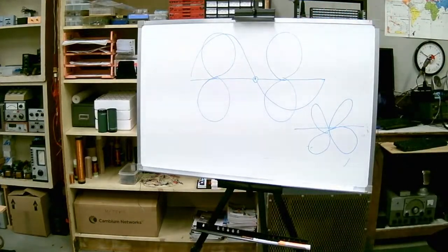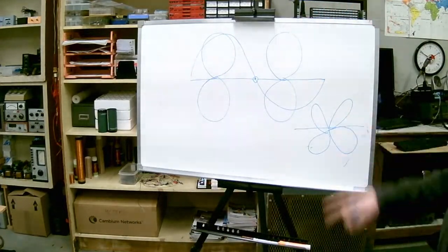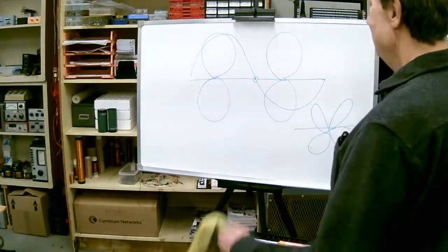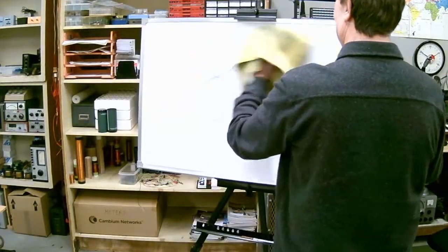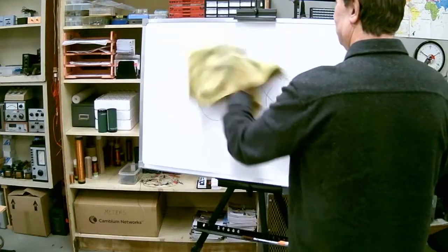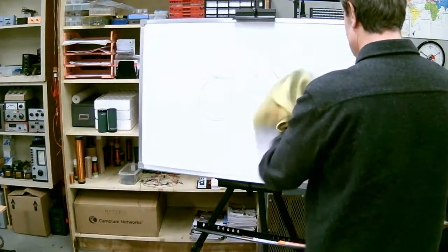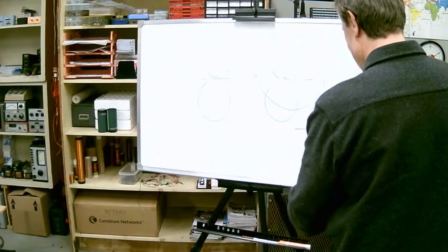Does that strengthen the signal in those other areas? It does, yes. You do get gain. Now, if we want a lot of gain, we just make the antenna really long. And that's what the oldest antennas are. There are a couple of ways of doing it.